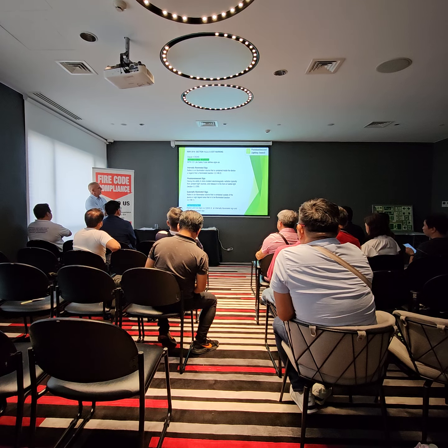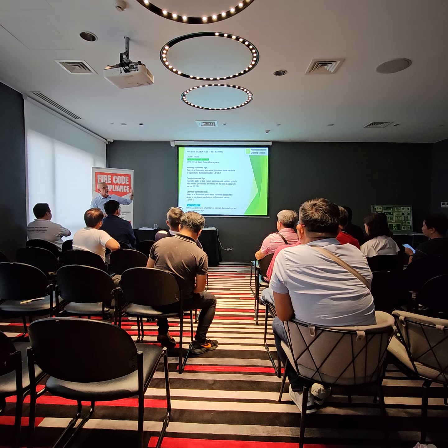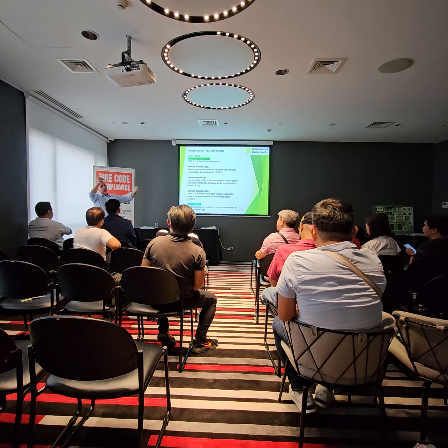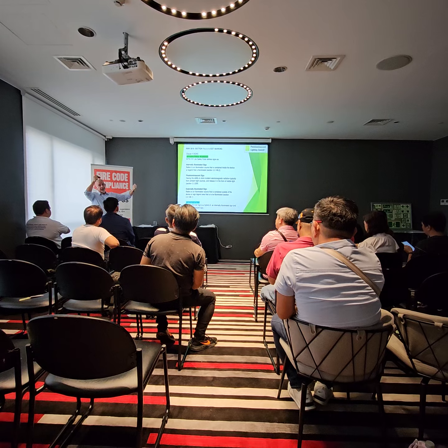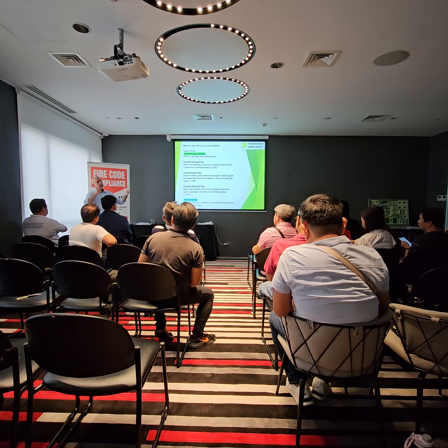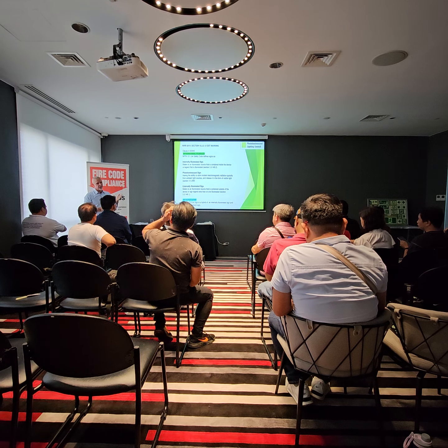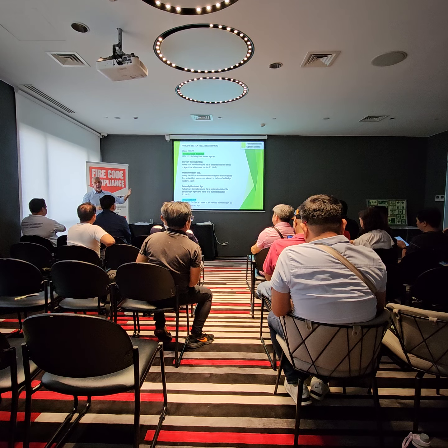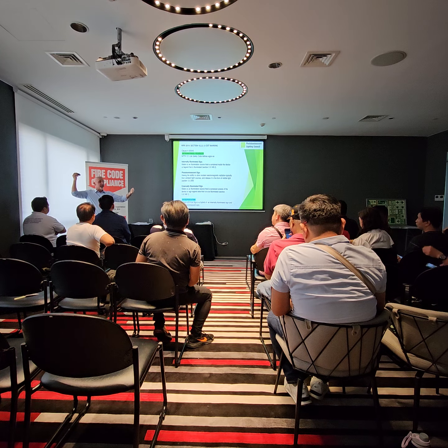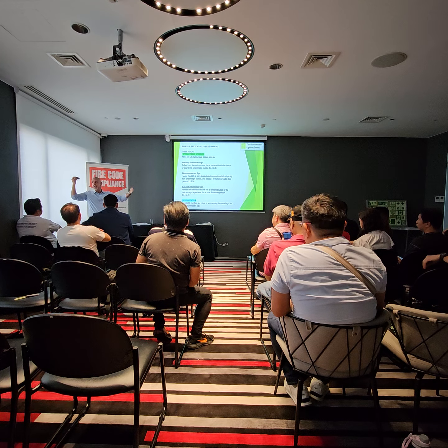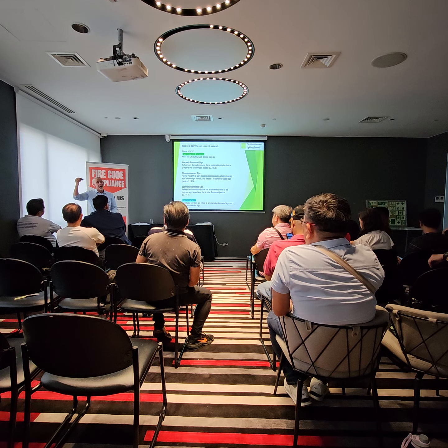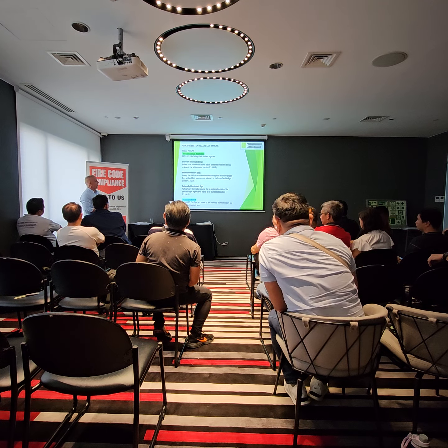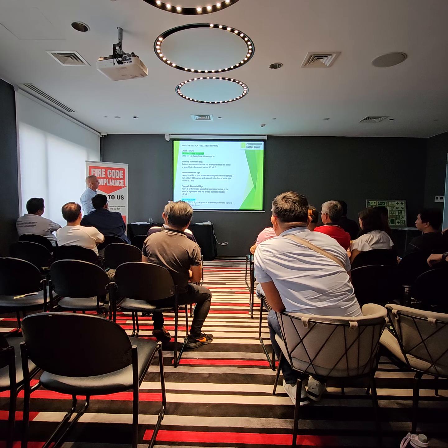An externally illuminated sign could be just a piece of cardboard with a print on it, but it has to have an emergency light that's going to operate for 90 minutes shining on it. Now, those sorts of signs are not used very much anymore for a number of reasons. One of them being the smoke reason, because if you have a light over here and the sign there that's meant to be lighting it, and you've got smoke, it's going to go up, it's going to block the light very quickly. So it's going to be even less visible than an internally illuminated one.